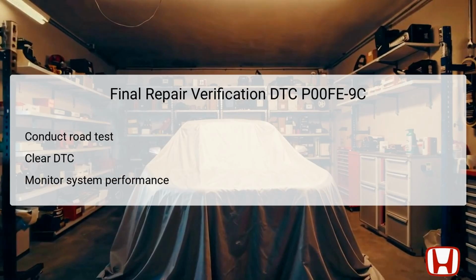After addressing all identified issues related to DTC P00FE-9C, it is critical to conduct a final repair verification. Start with a road test to observe if the problem persists and ensure that all systems function smoothly.